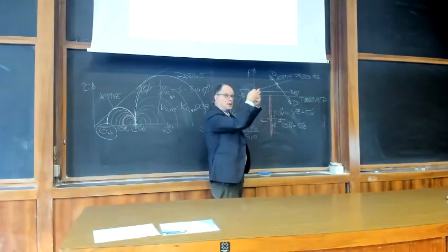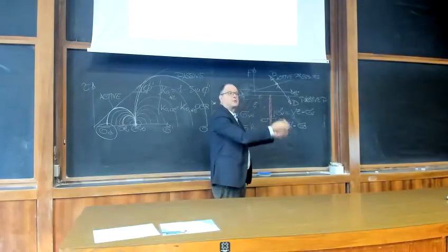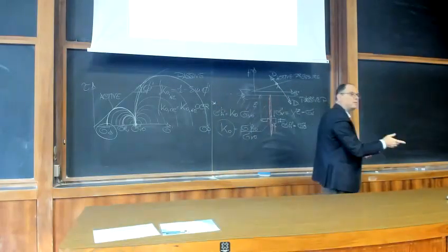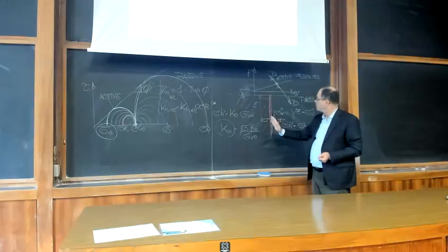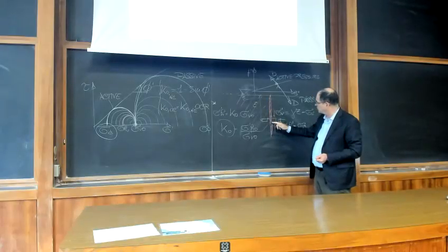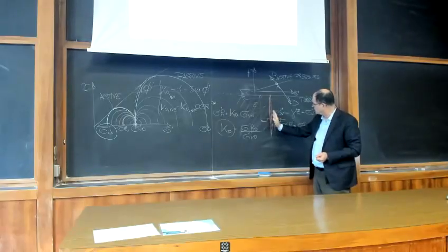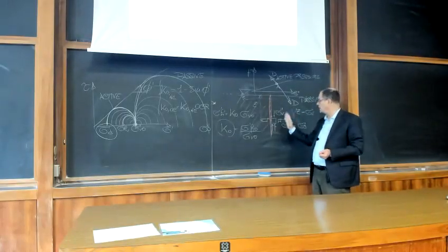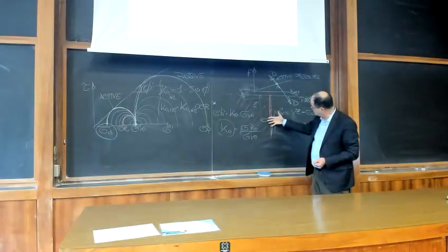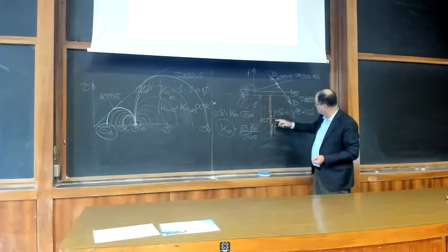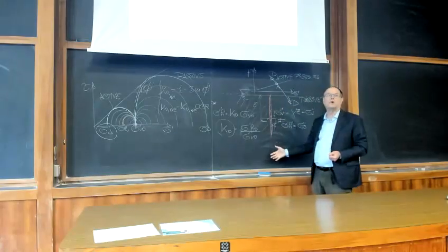A wall, perfectly vertical, no friction, exactly the same assumptions we have introduced in the previous slide. Now you have a wall, and this wall can move. Why does this wall move? Because you have a horizontal stress acting against it, so the wall is acting against the soil, and the soil, for equilibrium, is acting against the wall. So you have a horizontal stress here, horizontal stress here. You have this sigma horizontal stress which acts all along the wall height.